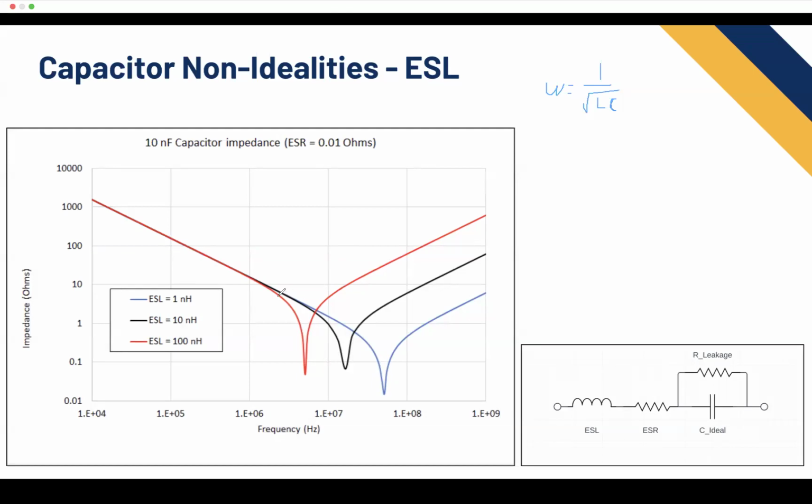So when the impedance drops off like this, then this one starts to have high impedance again, but now this one has low impedance. So you could just go down this path instead. And this one starts to go up, but then this one has low impedance. So you could sink the transient into this step, and then they all come back up. So it gives us a band stop filter where any transients in that frequency range will get taken out.